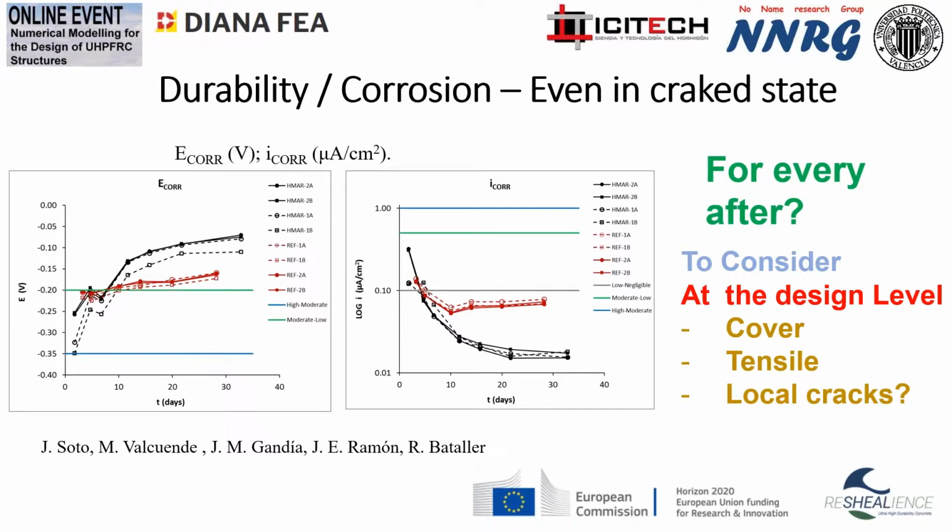And you must think that your concrete, of course, without cracks is forever, but you never need to work for forever. You need to consider your service limit, and then you need to consider reducing covers, or consider options of working with the crack in serviceability, even for pre-stressed elements. If you do that, you can design in a competitive way.